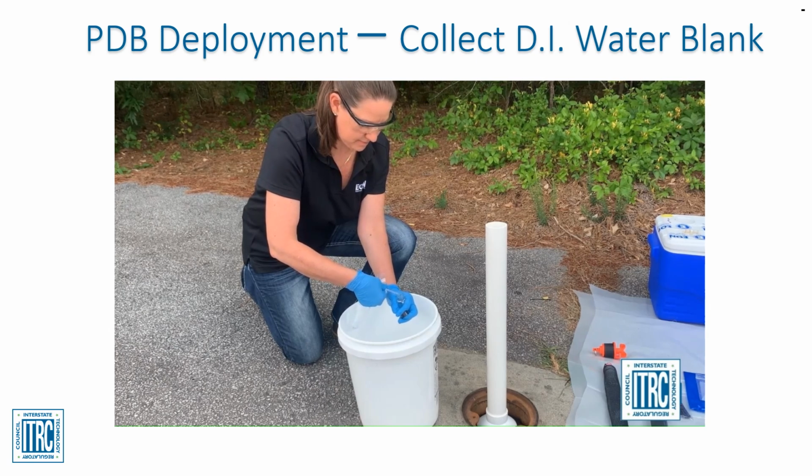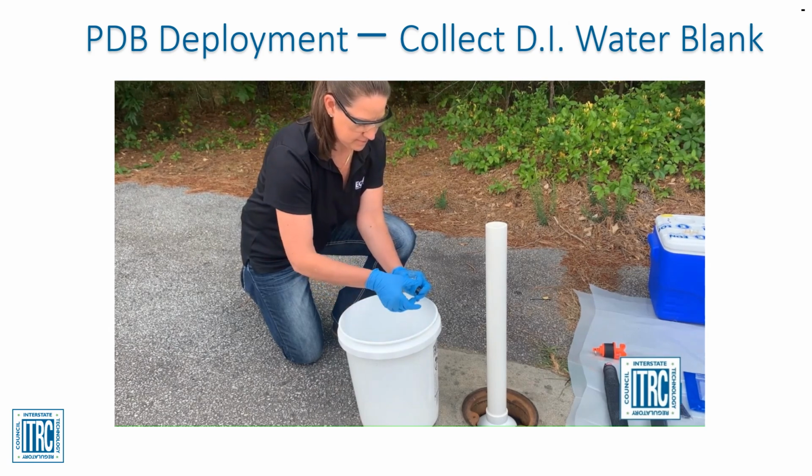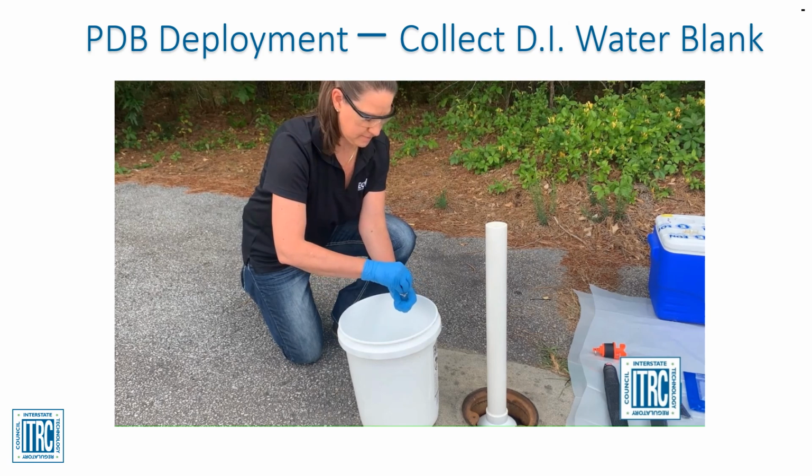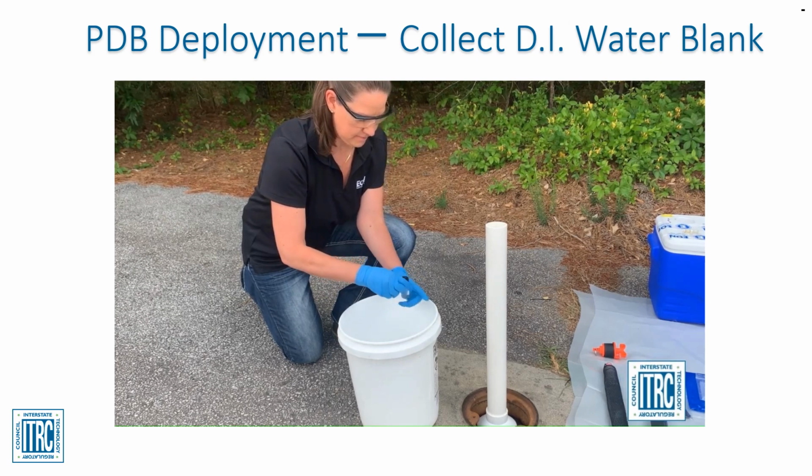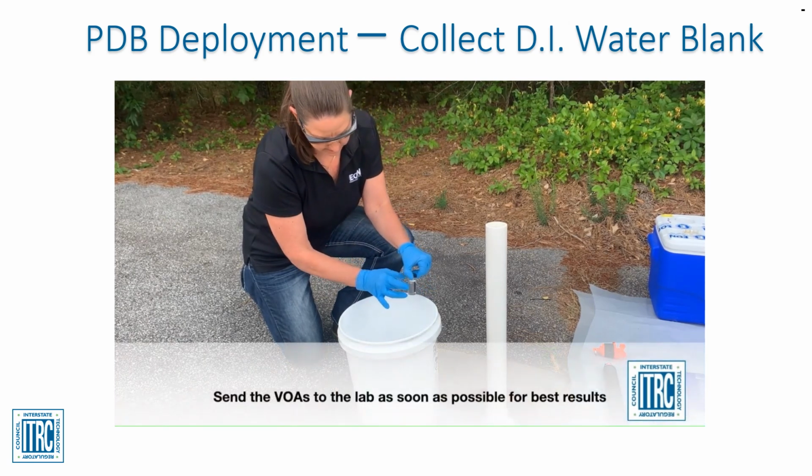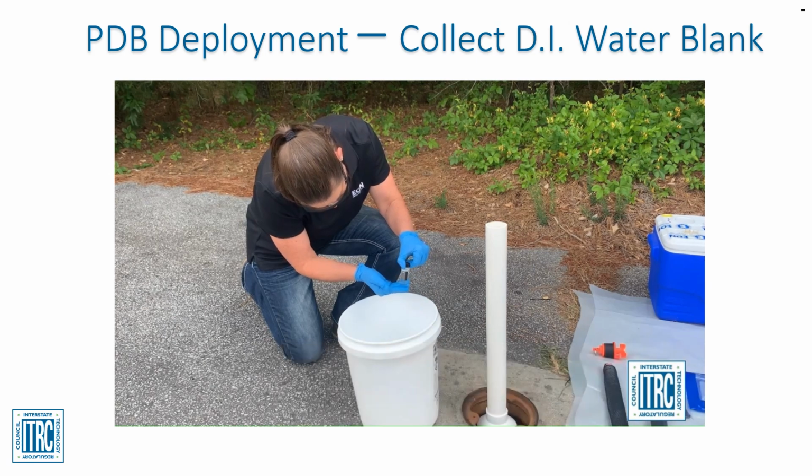If the PDBs are purchased pre-filled, order a DI water travel blank with the PDBs. Travel blanks are made from the same polyethylene membrane material as the PDBs, contain DI water from the same lot, and are exposed to the same environments during transportation to the well site. If the PDBs are filled off-site, it may be best to use the contents of one PDB from each water batch as a travel blank that is discharged to a lab bottle at the site. If the PDBs are filled at the well, sample from the water container.